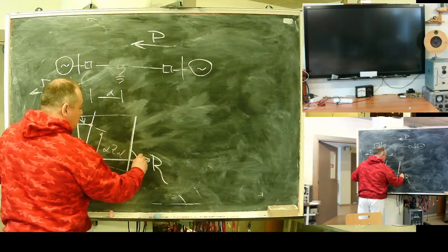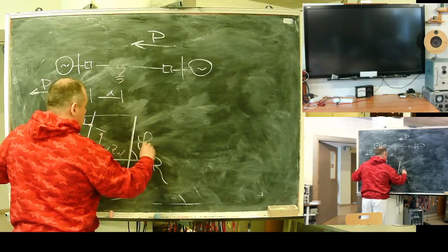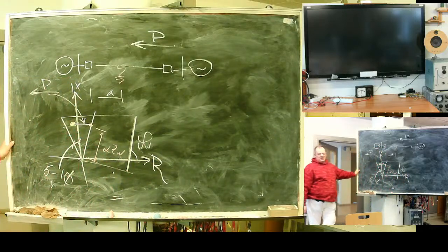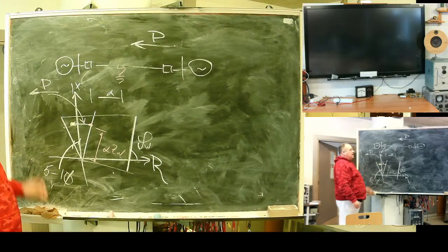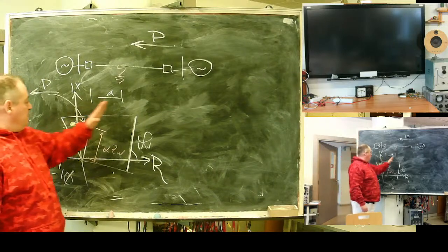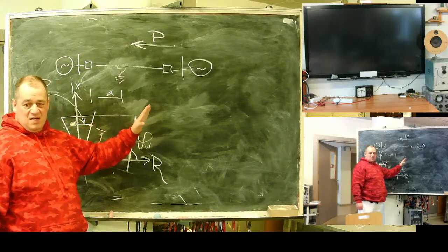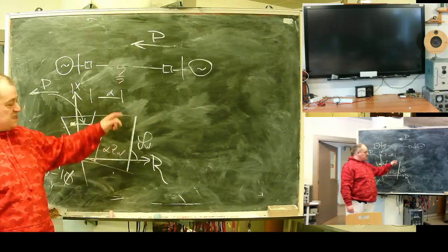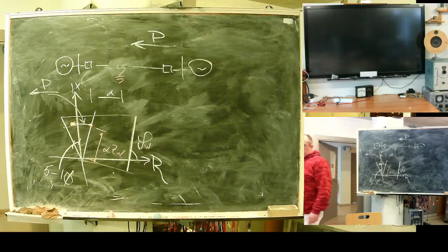While this one has our line angle, actually you can slope it a bit. It's from the nature of arc. The higher the current in the arc, the less is arc resistance. So at the end of the line, current will decrease, and you may add a bit of angle, because probable transient resistance at the end of line is a bit higher than at the beginning.